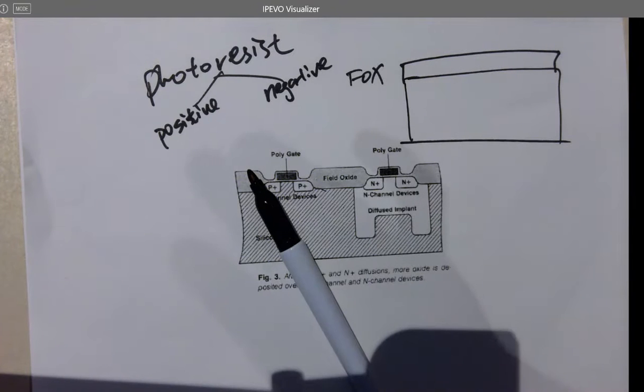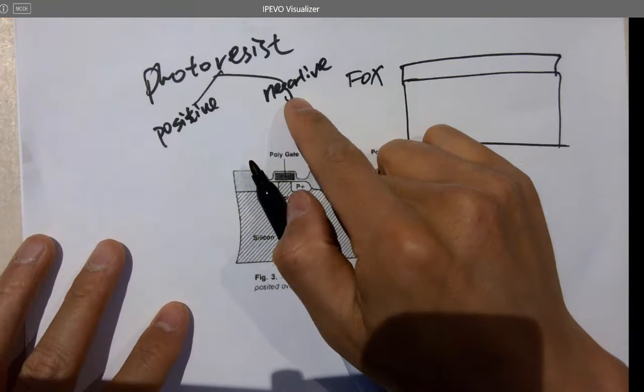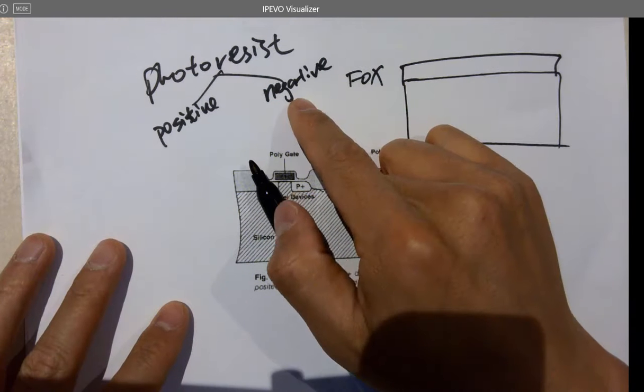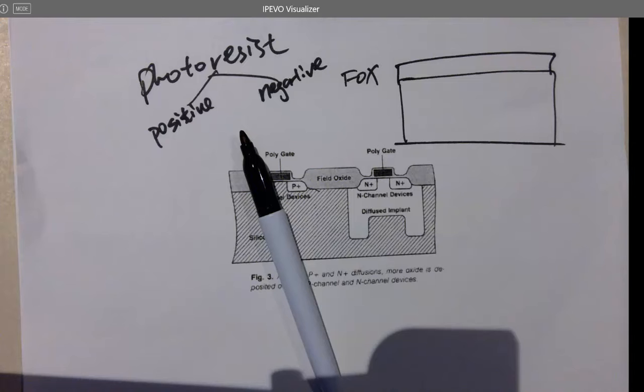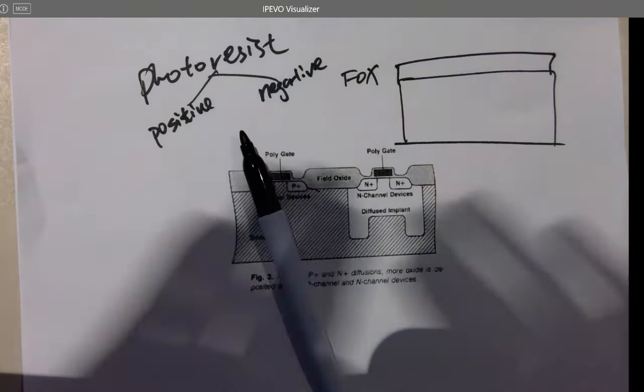And the cheaper ones can be just a clear plastic film. And so for example, if you are using negative photoresist, whenever you draw, after you print out the whole circuit, then whenever there's a wire, it shows clear on the mask.